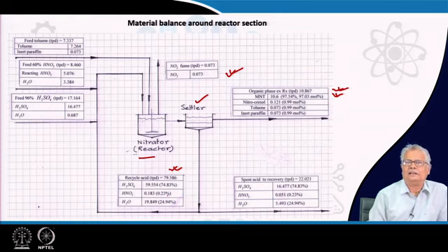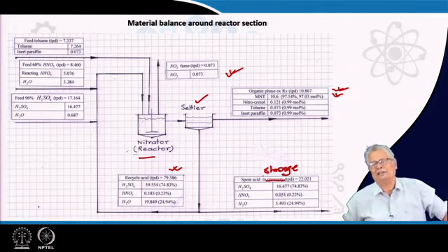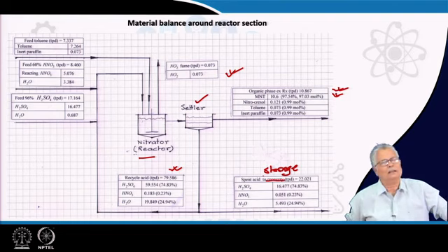You will note here a spent acid to recovery section. Basically, it's not exactly a recovery, you can call it, it will be going to the storage section for selling later on, and will be approximately 22 tons a day. So, you are going to send out roughly about 22 tons a day of spent acid, which will amount to about 20 meter cube. So, you will be sending out roughly one tank truck load of spent acid out of your factory.